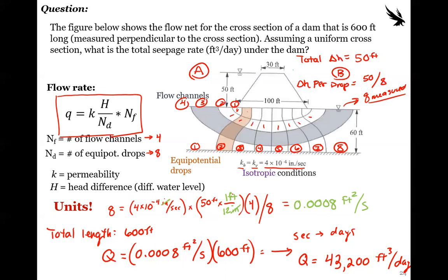You can see that. So each one of these little drops, if we wanted to find the head right here, halfway through the point, the total energy head right there, then how many drops do we have? We have 1, 2, 3, 4 drops. So that means we would have an equal amount of energy dropping through each one. So we can find the delta H per drop and then multiply that by 4, and that would be what it was. But what you'll see is that's generally going to be a linear interpolation between those two, if we draw the diagram correctly.